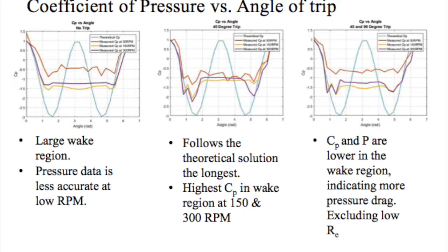Our group also dropped the cylinder after the no-trip data was collected. The higher RPM no-trip data is much smoother than the data at the same RPMs after we dropped it. The tripwires cause turbulent flow, but dropping the cylinder must be mentioned as a source of error.